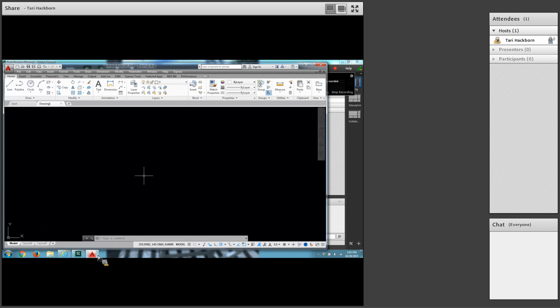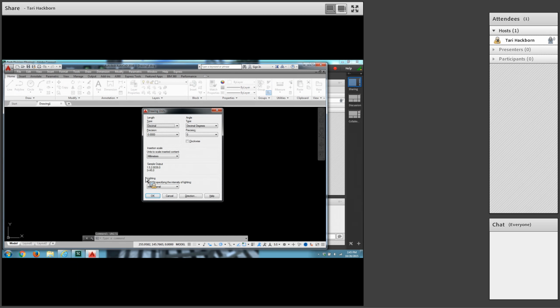Okay, turn to page 48 in the small book. This is going to be the demonstration for the 3D solids. It's a very long demonstration. Disregard everything at the top and just jump down to the bottom where the blue step 2 is. Type units and enter, and you can see that they want architectural units. So I'll get that right here.